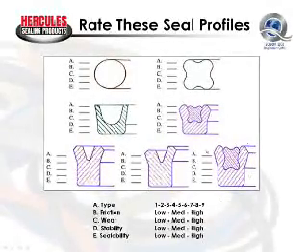This particular seal, also a rectangular seal, so stability is very high. It gets its performance advantage from the standpoint that we now have an energizer in the seal, which significantly increases the radial loading of the sealing lip against the sealing surface. So it's a pure squeeze seal, probably an 8. Friction is high, wear is high, stability is very high, sealability is very high.